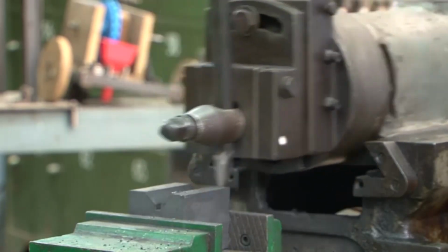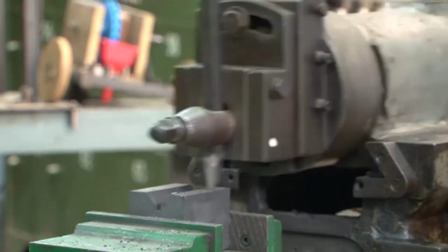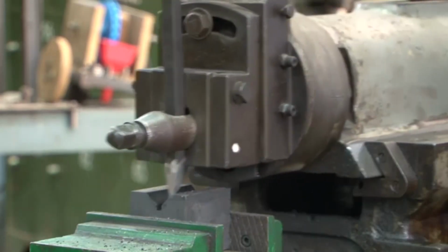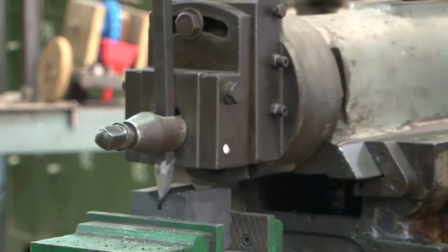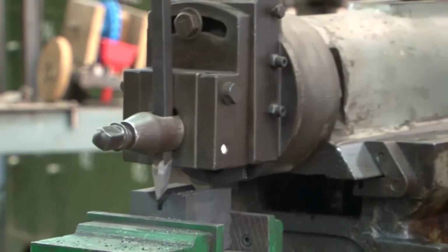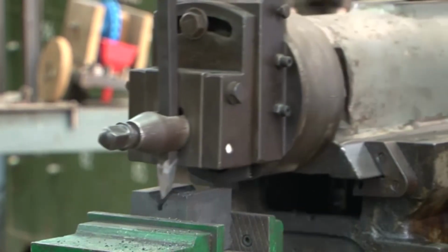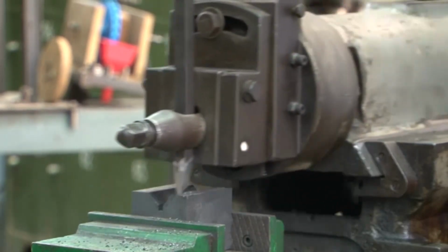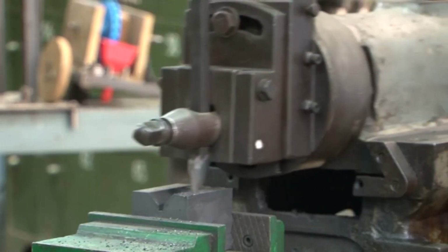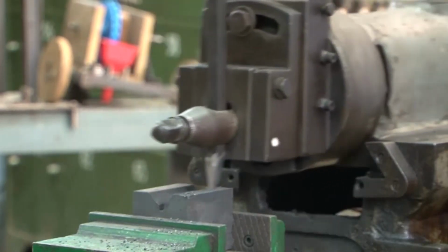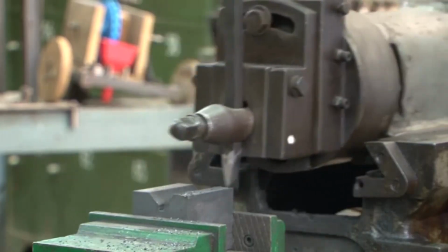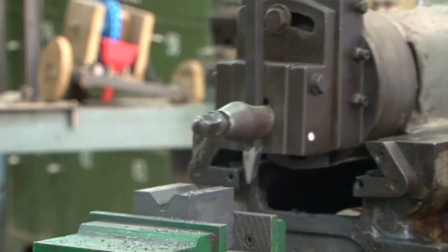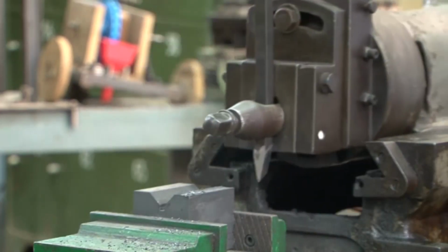Okay, now you can see that in each stroke, that is going forward and coming back, some material has been removed depending on the depth of cut that has been given, and a certain amount of material is removed. So, after each stroke, the tool is moving along the width of the workpiece for the next pass to happen and for the next width to be removed, so that the entire surface ultimately can be machined and the flat surface can be fabricated.